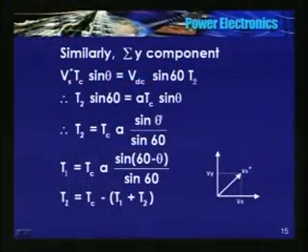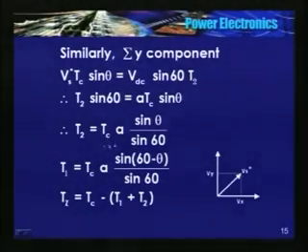So see, only theta should be known here, the position. The magnitude of the space vector that should be realized is known from the V by F curve. Vdc is also known. Therefore A is known. Tc is the sampling time, that is also decided. So I need to know the position of the space vector in the xy plane. If I know theta position, I know T2. I can calculate T1.